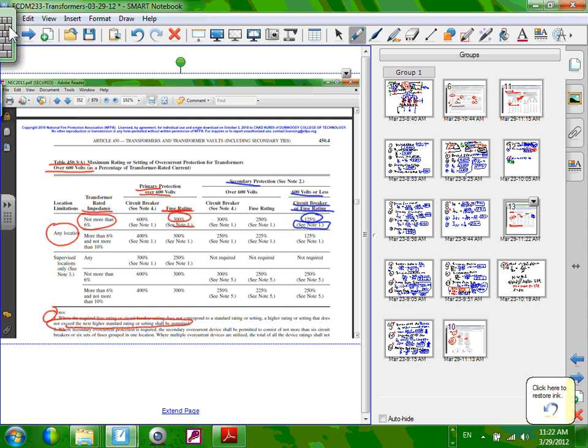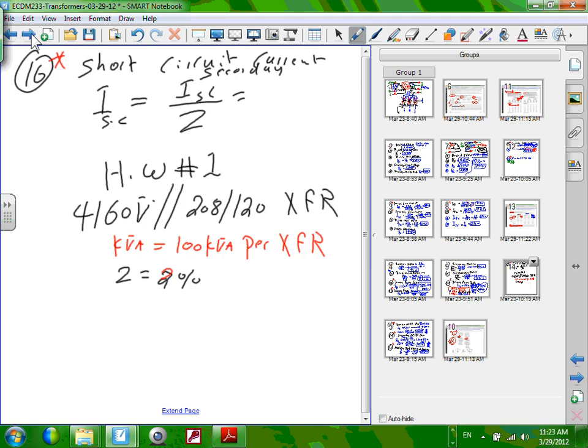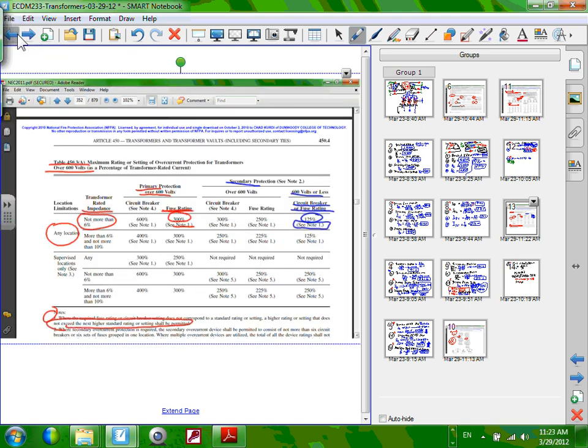Circuit breakers are more expensive than fuses. Yes. They let you run that up to 600%. So you're really okay on that. That's why I say it's really misleading, because at this level, you size by relays. They don't even make less than 600 amp medium voltage. So you start with a big circuit breaker and you size it with the relay, tweak it with the relay. It's not like you can buy a 15 amp medium voltage circuit breaker. You start talking about 600, 1,000 amp, and then you start reducing them. They're very adjustable.